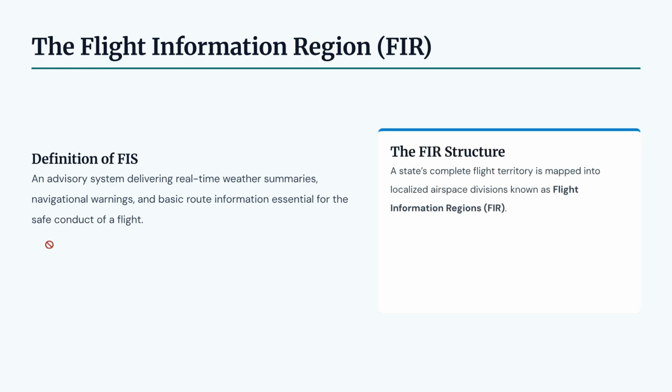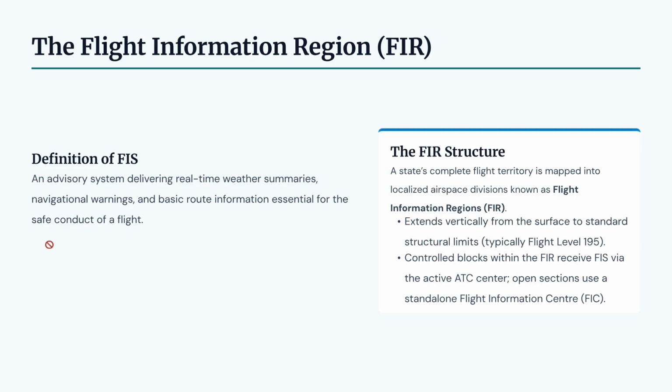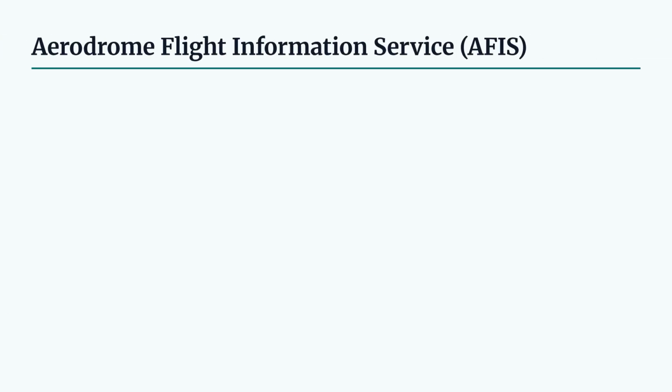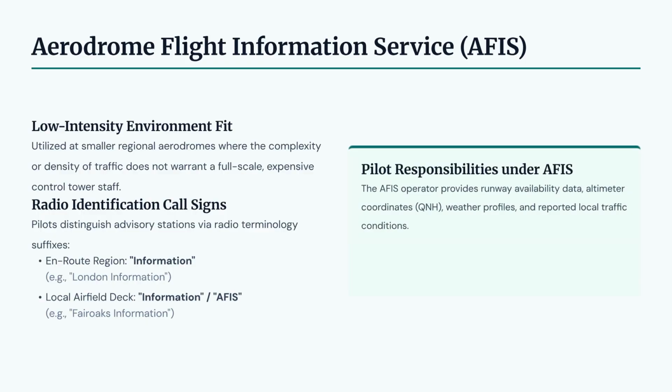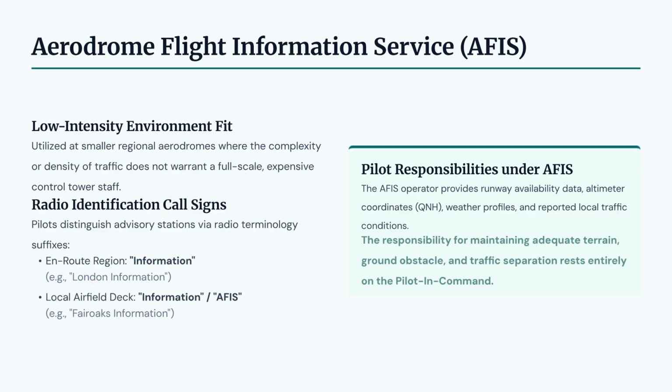The FIR extends vertically from the surface and may be serviced by an ATC center in controlled blocks or a Flight Information Center in open sections. Aerodrome Flight Information Service, AFIS, is used at smaller aerodromes. An AFIS operator provides runway availability and weather data. However, the pilot in command is entirely responsible for maintaining terrain, obstacle, and traffic separation.